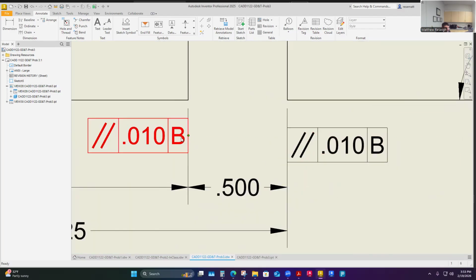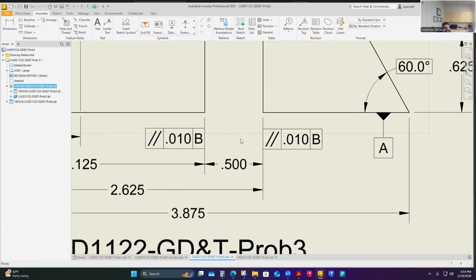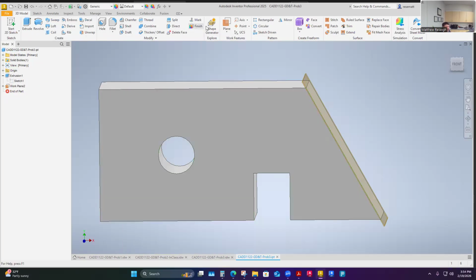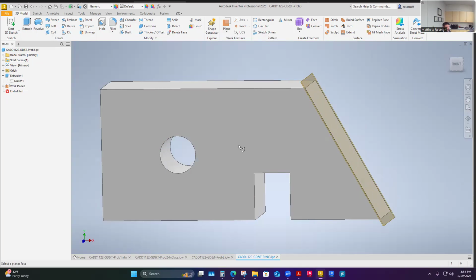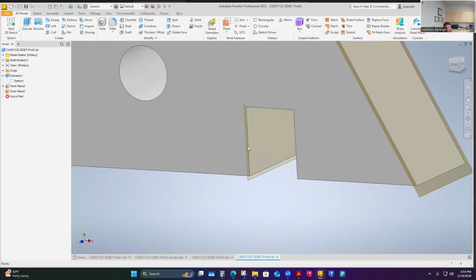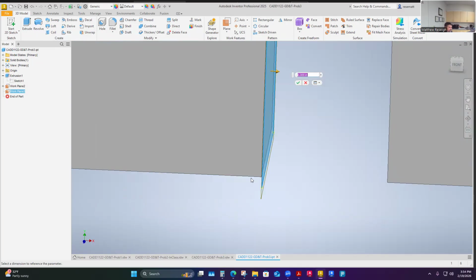Just going to eyeball, those are roughly the same. So there's two geometric controls. All that says is, yes, same kind of plane, only if I put it here, it's the same tolerance. So it's like here, 0.005 or half of 10, and then offset the other plane. And I'm doing this control on both, so I'll say it's a minus 0.01.